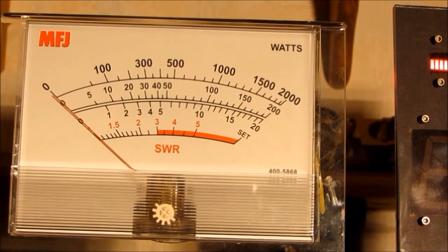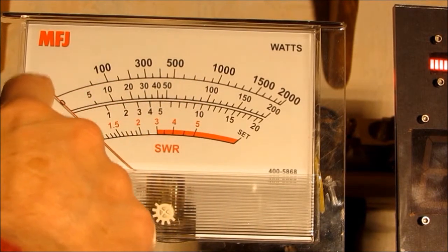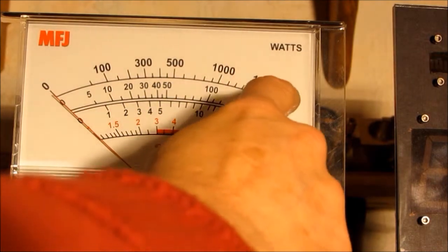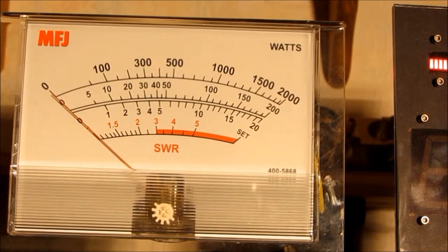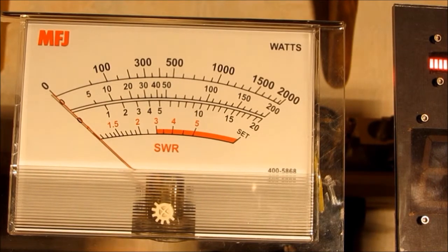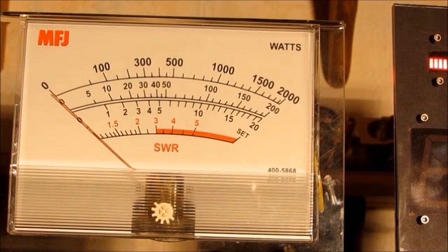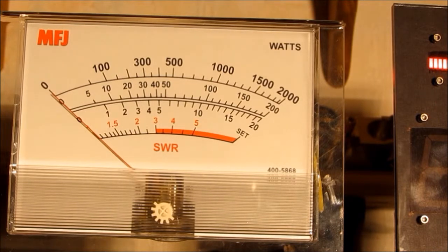Okay, the challenge with a meter like this that has a nonlinear scale for power and a different nonlinear scale for SWR is to pick the number of points that you're going to use for each scale. You pick those numbers in two different ways. First of all, depending upon the amount of nonlinearity, the more nonlinearity, the more points you need to do the piecewise approximation. The other thing you want to do is pick the number of points so that the settings don't drive you crazy during setup.